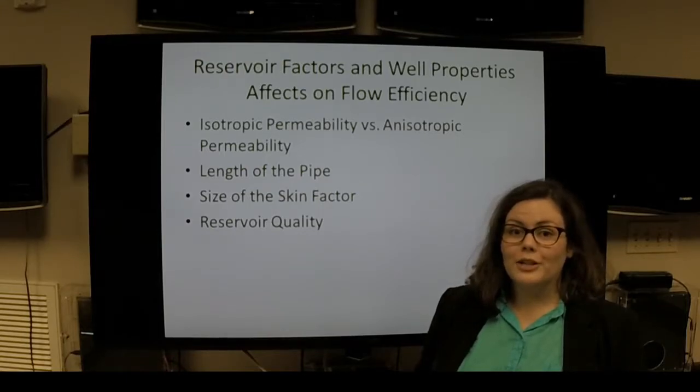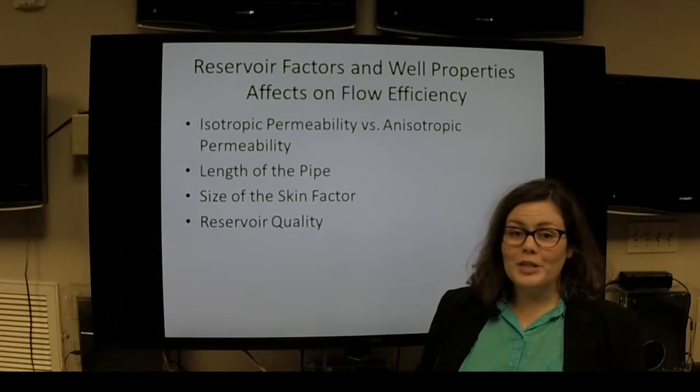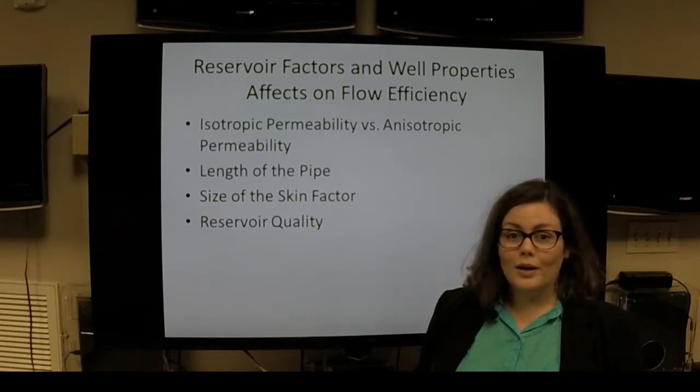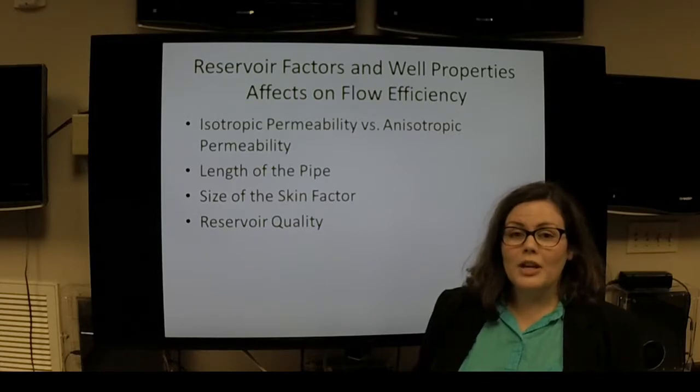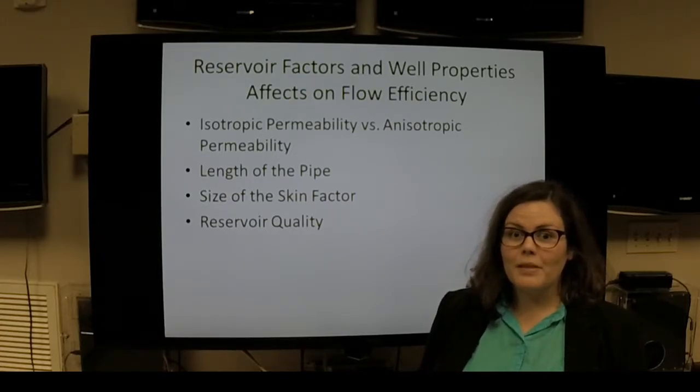Depending on whether the direction is all in the same direction or varying in directions can greatly affect your flow efficiency. Because with a skin factor or formation damage, having something in all directions versus in specific directions can greatly affect your production, especially in a horizontal well. Because of the damage and the blockage it causes, you can have a decrease in production, thus having to stimulate the well to even get a flow at times.